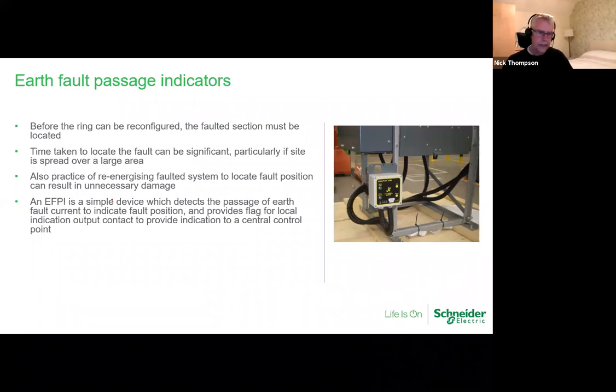So if it's an existing site that's been there for over 30 years, maybe 40 years, and the HV circuit breakers have not been changed from the original installation, which possibly could be oil, you're looking at a maximum of 3 full fault interruptions before you need to maintain or replace the contacts. Well, you might have already had 2, and then you're on your 3rd with re-energizing, and it trips again. So therefore, you're potentially going to exceed its capabilities, and it may have disastrous effects on the mechanism or the contacts or even the whole circuit breaker. So that's something to bear in mind.